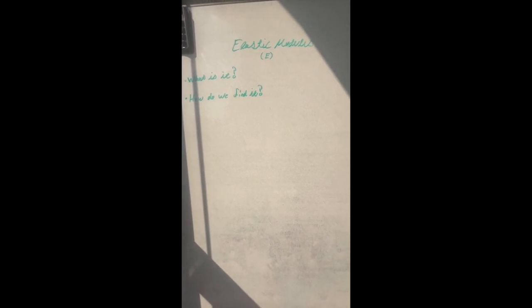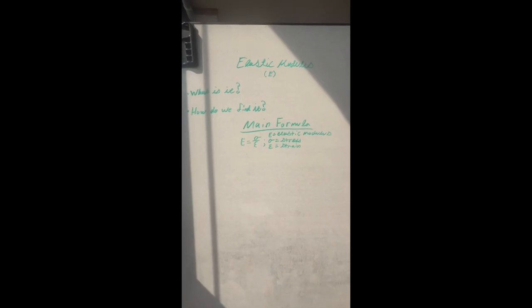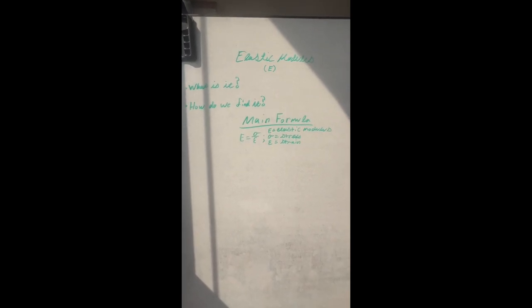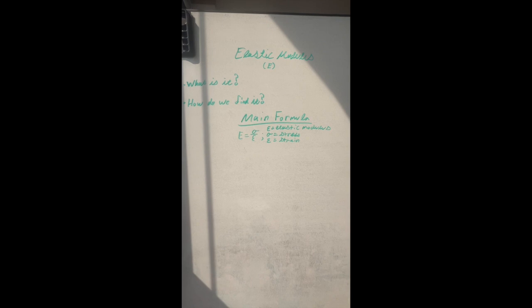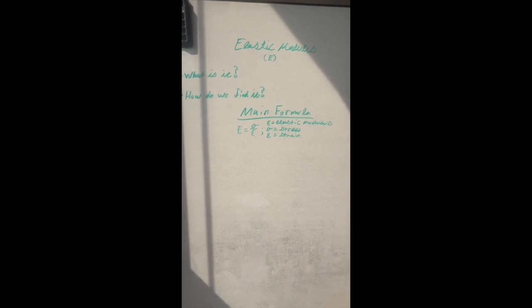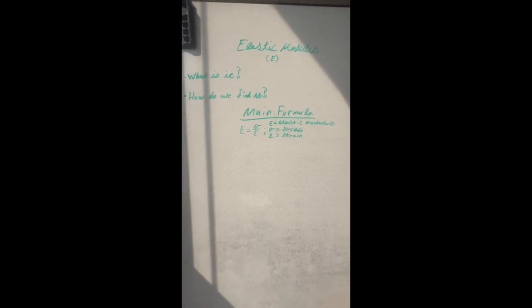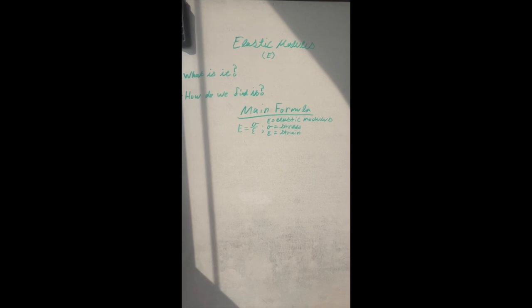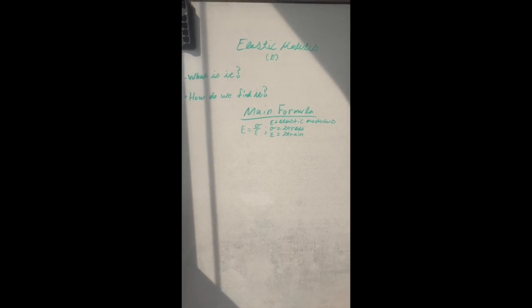Well, in this situation, we'll determine the slope using the change in stress over the change in strain, where the data points will come from the elastic region, which we defined as the linear line in the stress strain curve. So to find the elastic modulus, we'll use the formula E equals stress divided by strain, where we'll pick 2 points from the elastic region and plug those in. I'll show you in just a second how that relates to what we had previously on our graphs.